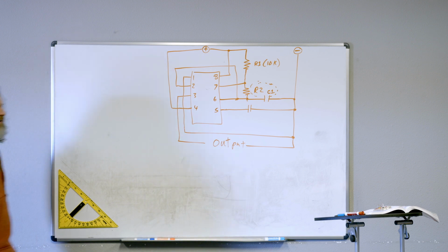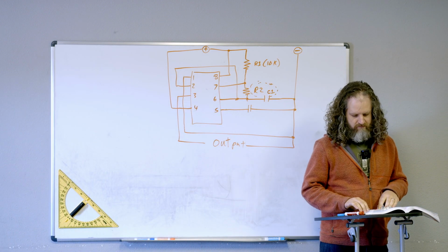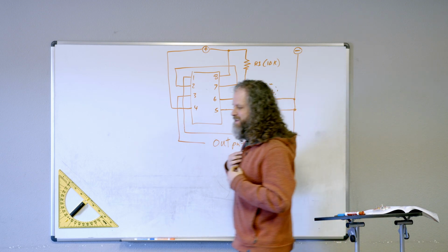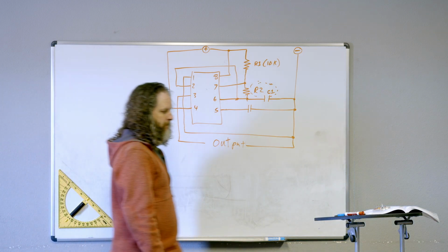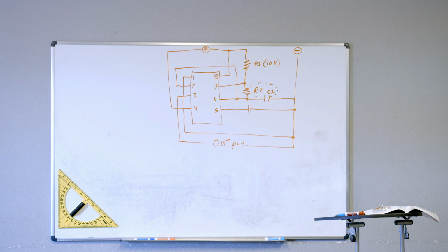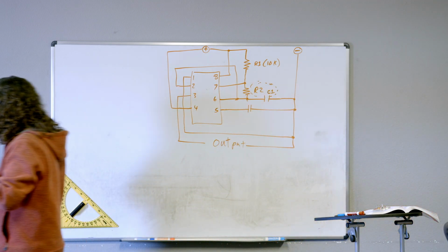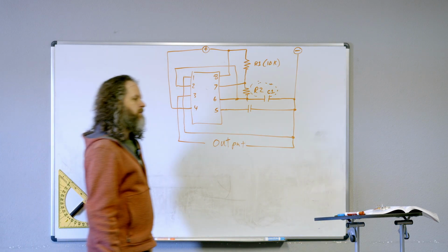Did you use a capacitor on pin 5, Malcolm, or did you leave it off? On pin 5, I leave it off. You should try it with a 0.1 and see if it still functions like you'd expect. Is 0.1 104? It'd be a 105. No, yeah, 104. You're right. I'll do that in just a second. It should still work just great, but why is it doing this?